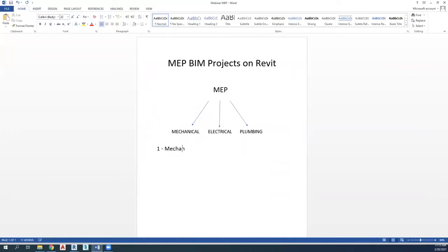Starting with the air terminals or the diffusers. Placing them on the ceiling provided by the architect. We will place the fan coil unit. And then we will draw the duct connecting the air terminal with the fan coil unit, adding the flexible connections, which in this case is the flexible pipe, connecting the diffusers to the duct. And finally adding the insulation.